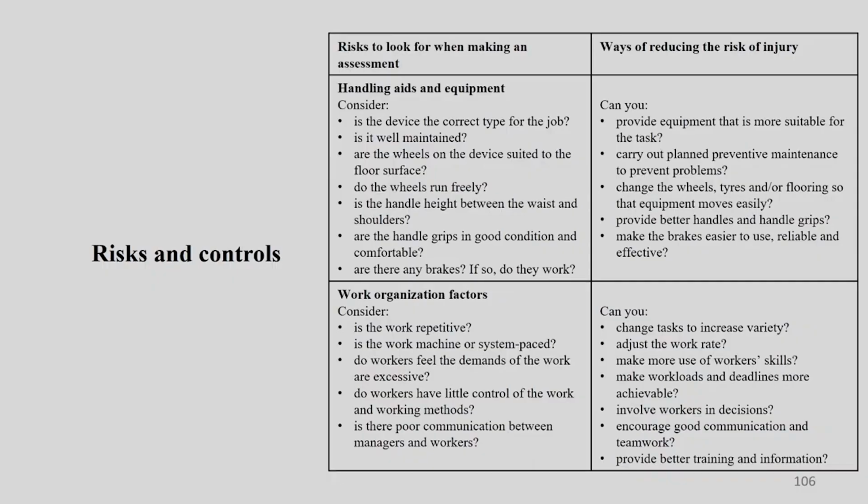Now coming to handling aids and equipment, you have to consider: is the device the correct type for the job or not? Maybe you have a forklift for lifting some kind of load, but there are varieties of forklift. So is that particular type suitable for that particular lifting or not? You have to find out.